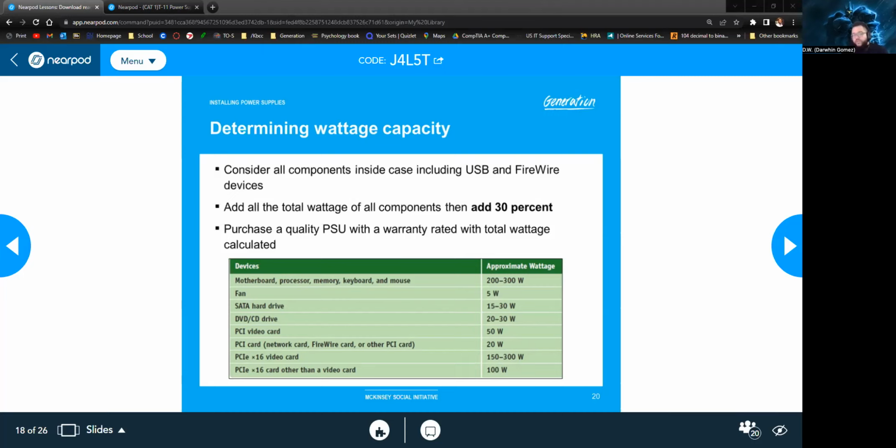All right, so you take 253.3 and add it to 845, and that should be how much wattage the power supply unit that you want to buy should have. About 1100. Exactly. So you would look for something with 1100 or a little bit above. You might need 1100, that might be the 30%, but the power supply unit might only come in 1200, so then you would go to 1200.